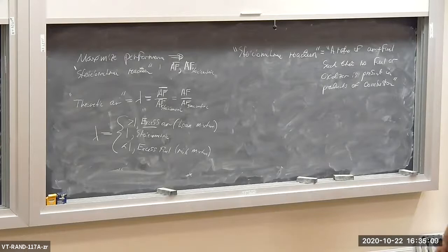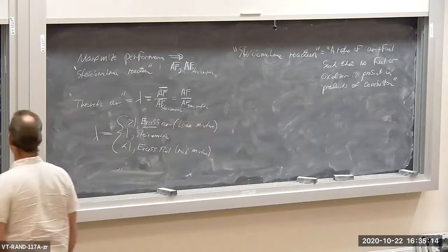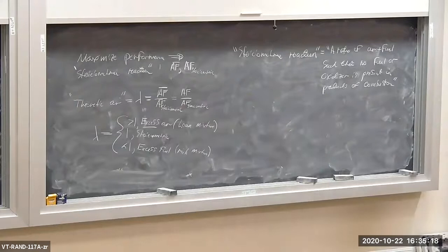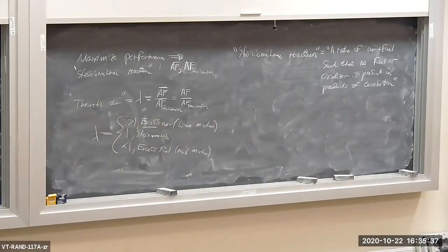If you want a little history here, in the old days, before we had emission control, before we had catalytic converters, before we had emission standards, typically to maximize power and fuel economy, automobile engines, the gasoline engine, tended to run ever so slightly rich, just a little bit more fuel than they needed. And that resulted in fairly high combustion temperatures, higher peak temperatures in the combustion chamber during the cycle.